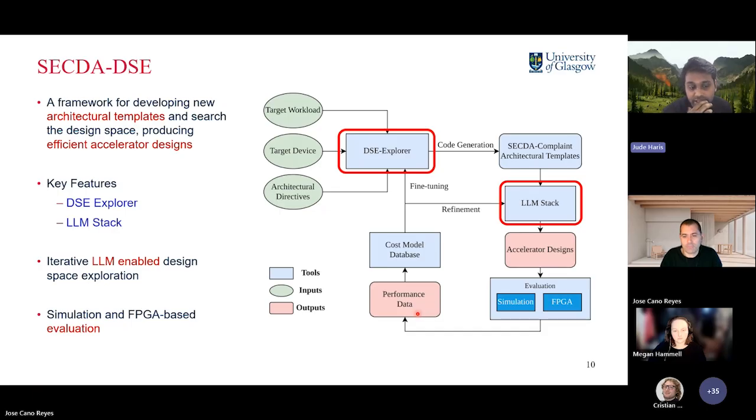The SECDA-DSE approach is an iterative design process, which is enhanced by the performance data, which we evaluate using SystemC simulation and also using hardware generation using high-level synthesis and logic synthesis. Now we'll take a detailed look into the DSE Explorer, and after that the LLM stack.